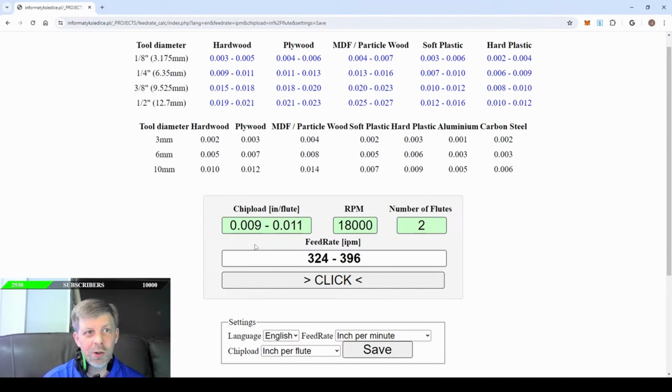Now, when you're clearing, a lot of people will use 40%. I've even seen some people use 50%. And while this will clear faster, do know that in a hobby style CNC machine there are pressures that are affecting chip load after about 30%.